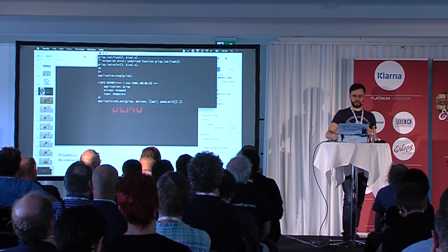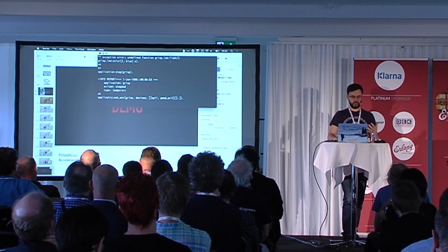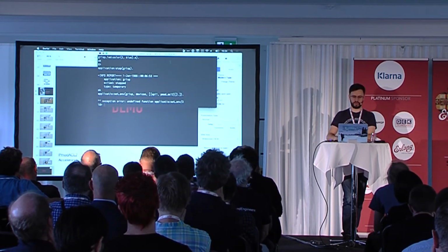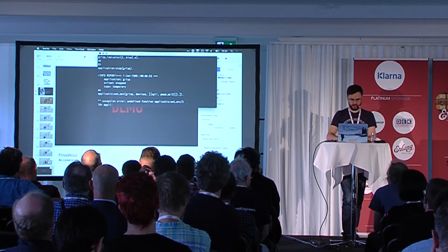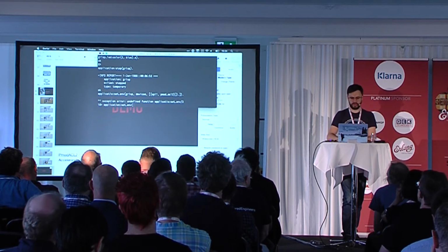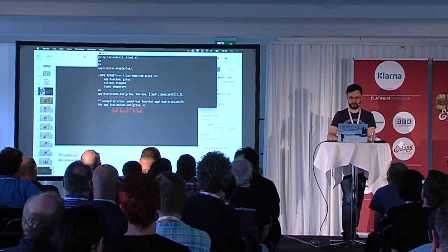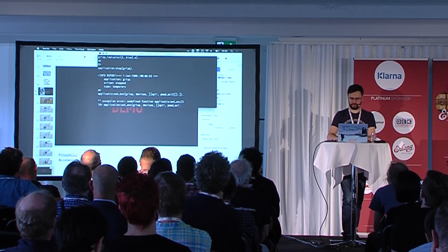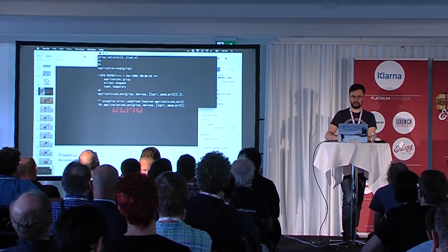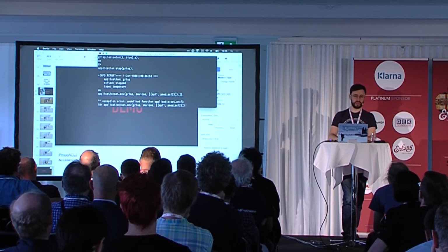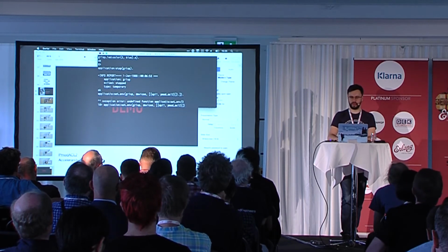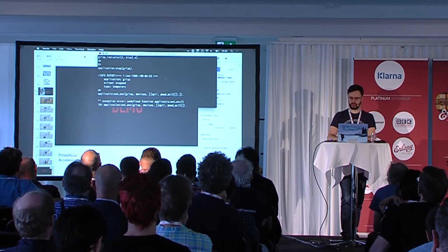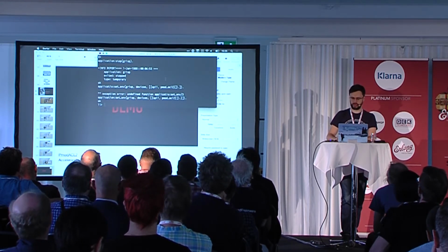So that tells the GRiSP runtime to, when it boots, also start a driver instance for, okay, I misspelled. So let's do it again. The reason I'm doing it again and not just fixing the line is because the terminal emulator we're using is a bit stupid. It doesn't have proper line editing. This is just using the serial interface over the USB. You could use Screen, for example, to connect to it. We're using an OS X app called Serial, this one, because it has some other nice features like line editing mode and so on. But it's up to you how to connect to this one.